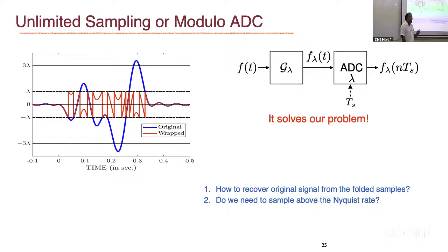So in that context, people talk about this, which is called identifiability. And they said whenever you have band limited signals, you can sample slightly above the Nyquist rate, and that should be good enough to get back the original signal from the folded version. Those are the theoretical guarantees. But in practice, algorithms work slightly differently. So we'll talk about some practical algorithm, what they usually use. There will be different recipes, but we'll talk about one simplest recipe. Okay, fine.